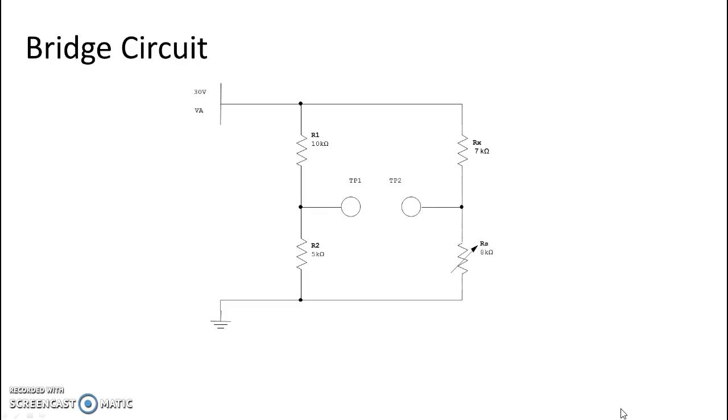All right, here we are, and we're taking a look at bridge circuits this time. So let's talk first about how a bridge circuit is constructed, or this particular type of bridge circuit. We have two series circuits connected in parallel, or two voltage dividers connected in parallel would be another good description. Since we just learned about voltage dividers, I don't think it's difficult to see why we would call those two voltage dividers connected in parallel, because you can see the two tap-off points there in our circuit.